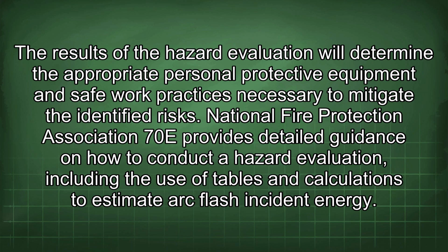The results of the hazard evaluation will determine the appropriate personal protective equipment and safe work practices necessary to mitigate the identified risks. National Fire Protection Association 70E provides detailed guidance on how to conduct a hazard evaluation, including the use of tables and calculations to estimate arc flash incident energy.